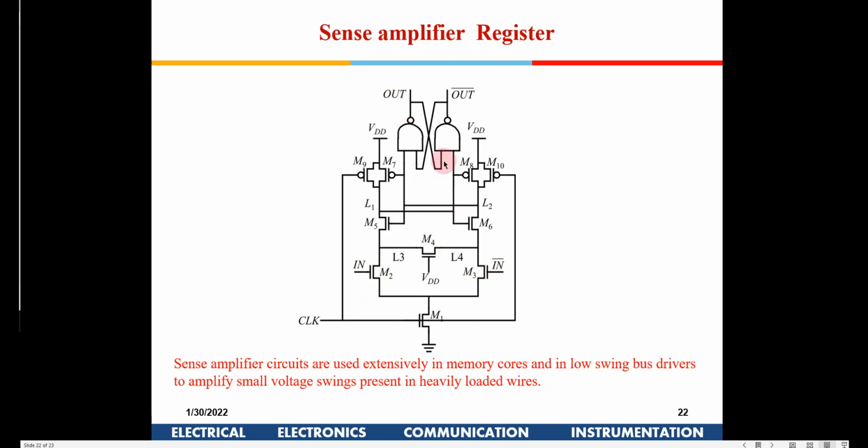So you can't connect the main data line onto those memory cells, because the data lines connecting the memory to the microprocessors will have huge interconnect capacitances. If you try to connect those lines directly onto your memory bit and bit bar lines, the data will get corrupted.